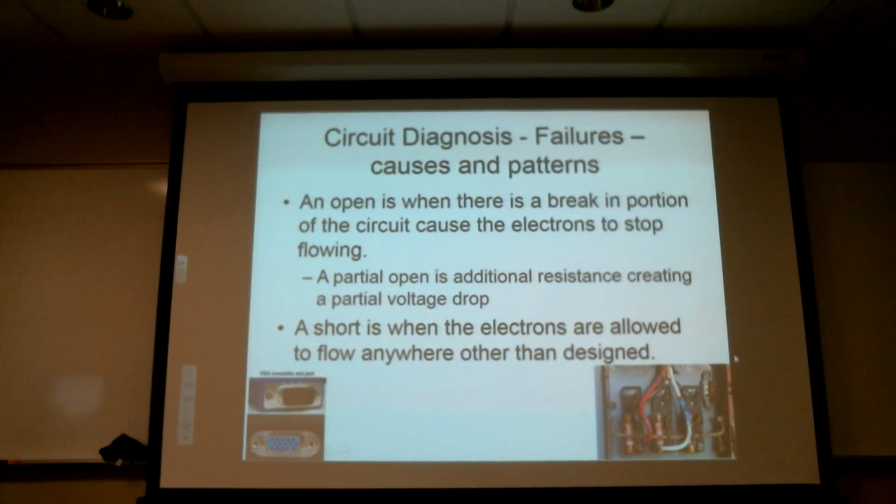Right? Do you know what the appropriate resistance is for a typical relay? No, but you might want to pull a new one off the shelf and measure it if you don't have that value. Do something to get a good value, because when you go to measure that with an ohm meter, you're going to read 2,000 or 3,000 ohms. Think, well, maybe that's right. At that point, the only thing you can do is go back and compare against a known good component if you can't find the data.